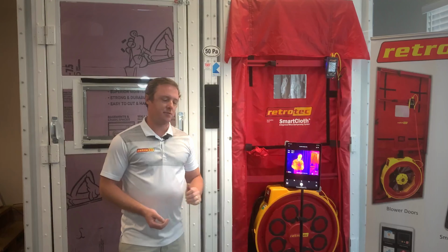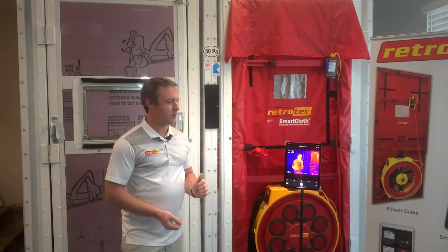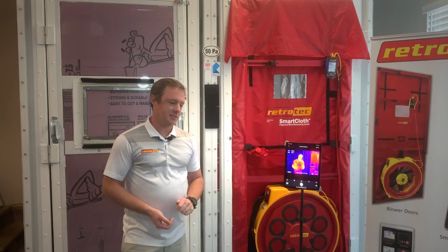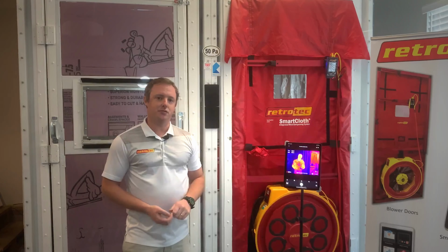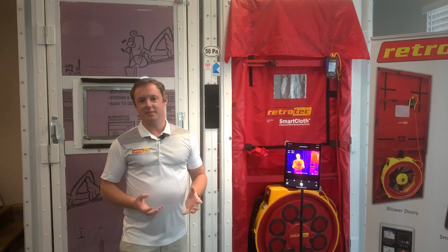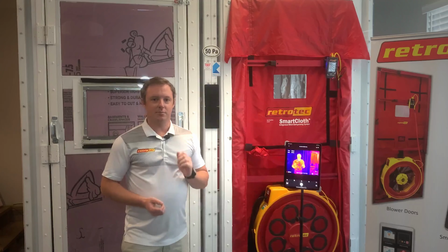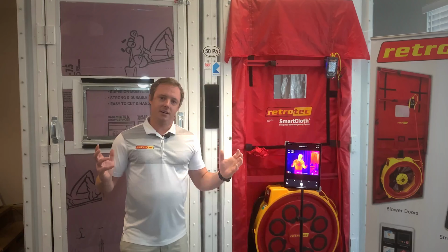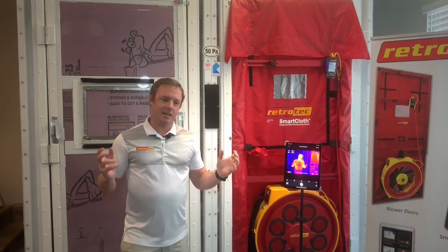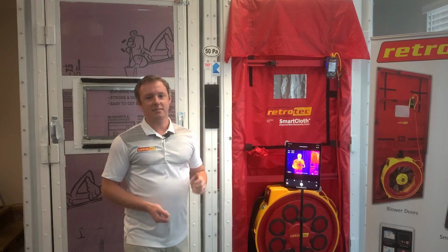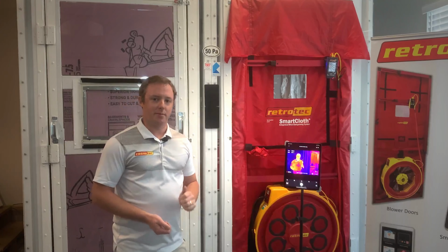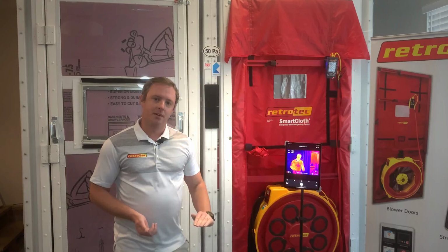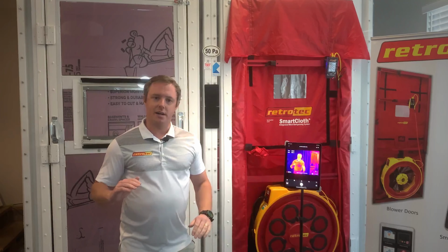But if you're going to use thermal imaging, you want to do that before you run your blower door test to measure leakage. The main reason is you don't want to over-exaggerate the leaks in the envelope before you shoot it with that thermal camera, because it kind of blurs everything. If you over-exaggerate those leaks like that, it can make it difficult to see exactly where that air leak is coming from. So one thing that Jay recommends is starting out low and then gradually working our way up.